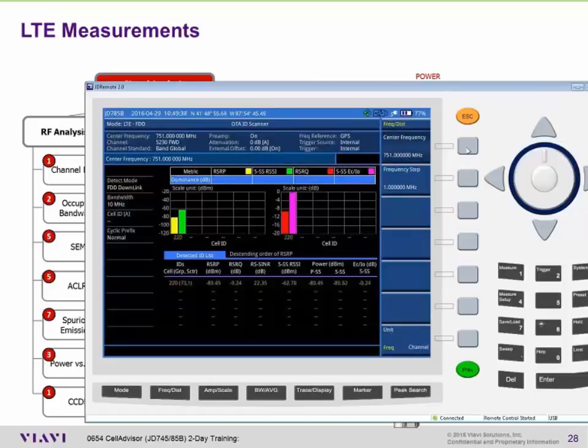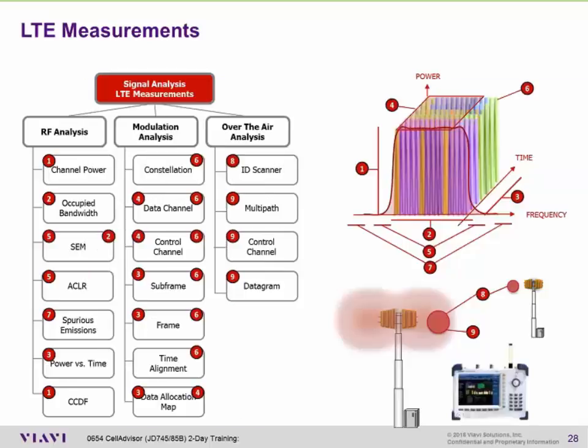At AT&T, I'm going to put in a center frequency of 739. They too are a 10 megahertz wide carrier here in the Chicagoland area. And let's see how well they serve me here at my home. Here we can see 330 and 331 are the primary two, but notice our SINRs are considerably lower. On the Verizon, I hedge towards one sector. Well, for AT&T, where this antenna is located right now, it looks like it's right in the middle of the two. So that's not ideal RF conditions for getting the highest possible modulation rates. So again, I wanted to share that with you before I move on.